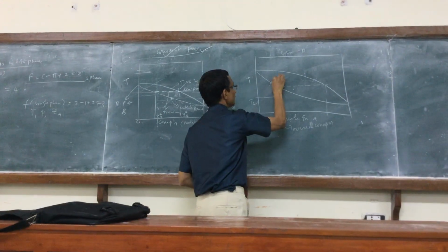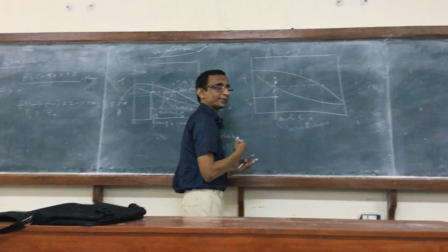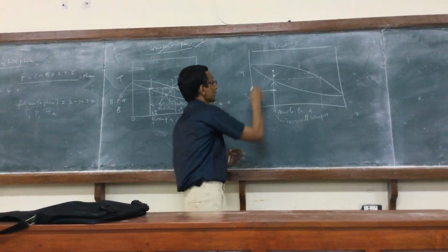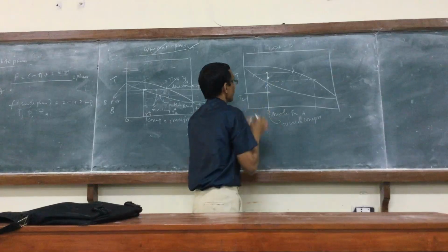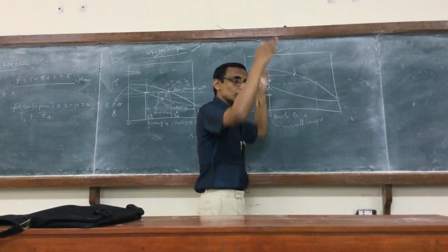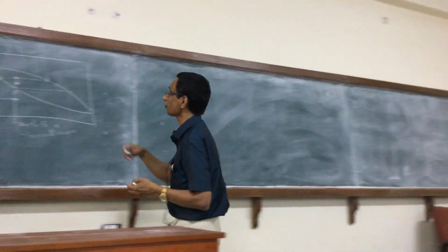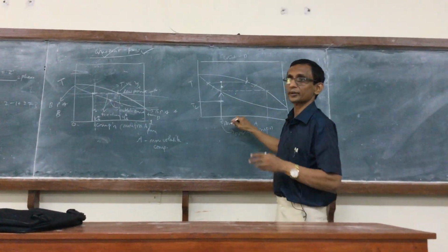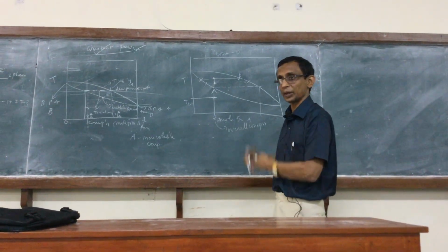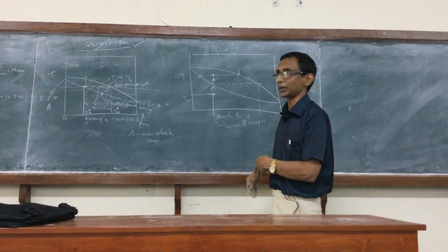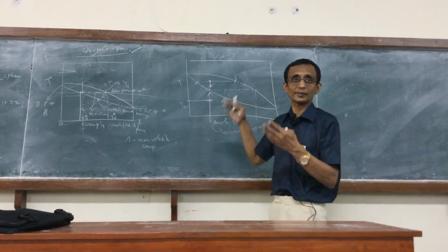So when I go here, this may be represented as the overall mixture, but strictly the only two points that have meaning are this and this from thermodynamics. There are two phases, but I can look at the two phases together as a whole system, and then you can easily verify that the overall composition, that's the total number of moles of A in the liquid and vapor put together, divided by the total number of moles of A plus B, will clearly be given by this, because I am not removing anything from the vessel.